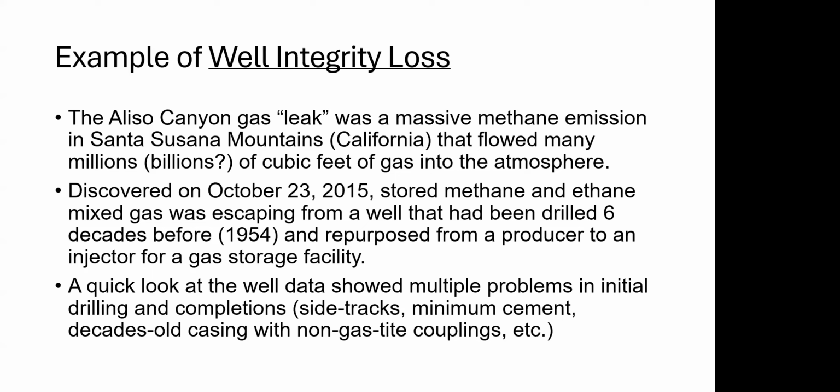My opinion was that I would have never used this well for this. I lived for a time there, about 700 yards away from one of the biggest gas storage areas in Texas. And I called them. I had a long conversation with them after this, and I asked him, "Well, what'd you do?" Because I know it was a lot of old wells. He said, "We plugged every one of those old wells. We drilled new wells into there, and we haven't had a problem with leaks." Now, those were some orphan wells that would have given you fits if you didn't know where they were, and they were not plugged and abandoned correctly. So a quick look at all this stuff will find some of the problems that you get into. Next slide, please.